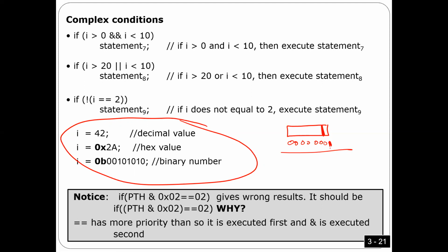Nothing is new, right? So here I'm going to get bit 0 and then bit 0, and then I'm going to get 0, 0, 0, 0, everything is 0. Then I'm going to check the value. If this value is 0, that means bit 0 is 0, otherwise bit 0 is 1. Make sense? That's what I explained before, and that's what we are going to do here in C language. So how can you do it in C? Okay, look how I'm going to do it.